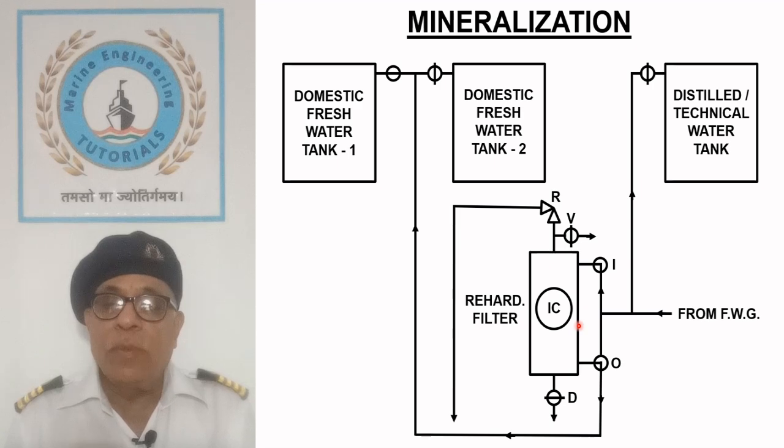Cylindrical shell is equipped with inspection cover IC for renewing calcium carbonate and connections for inlet I, outlet O, vent V, relief R and drain D. Rehardening filter has long service life and the calcium carbonate bed may be renewed when its effectiveness is reduced.